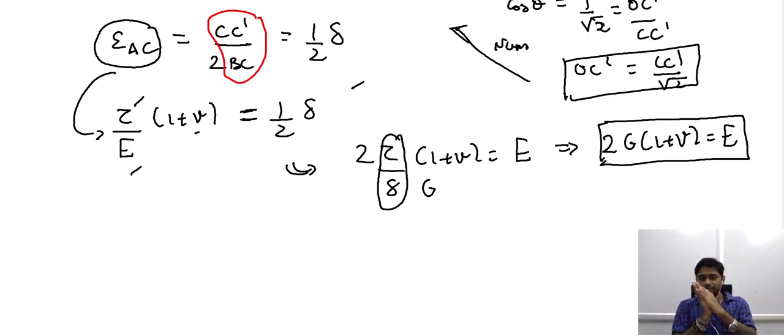And we have considered the deformation along the one element that has exhibited an elongation. This elongation is due to two factors. One is direct loading, the other is the Poisson's effect. The Poisson's effect is because of the other perpendicular element that is experiencing a compressive loading, and the direct effect is due to the shear stress. So we have combined these two and arrived at an expression for the strain along the diagonal element that we are interested in.